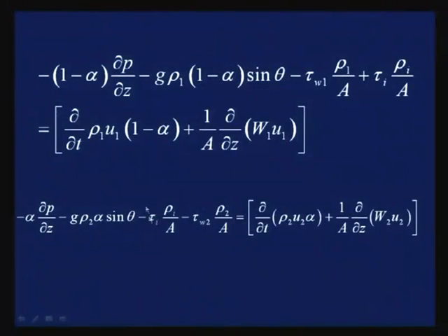Say suppose some particular fraction of it, say eta fraction of the liquid phase, is getting converted to the gas phase. So, W1 into eta is the amount which is getting converted, and this particular amount is changing its velocity from that of the liquid phase to the gas phase, or in other words, from u2 to u1. So, this mass flow rate into the change in velocity gives you the rate of change of momentum.